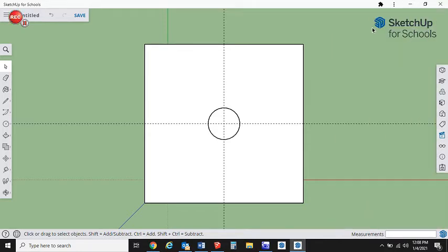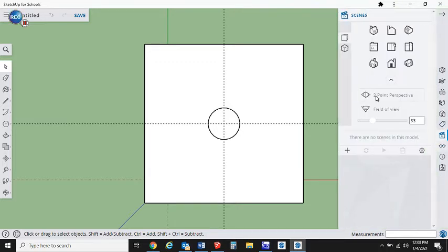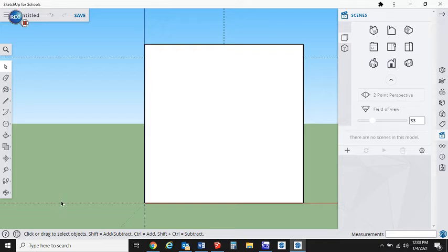Okay, next thing is we're going to now move to the number 4 side of the dice, so the front view. So we're going to click over here, we're going to find where our front view is. So front view would be the one with the door right here. Click on that, and then we're going to type in our user guideline, so type in T again, and we're going to create 4 guidelines 5 millimeters towards the center from each edge.